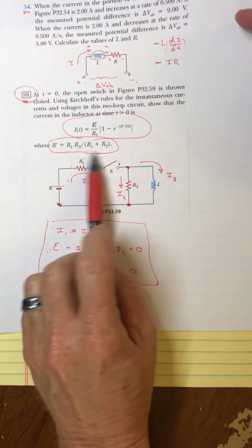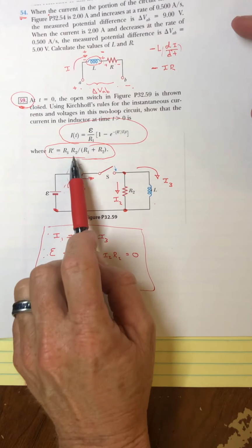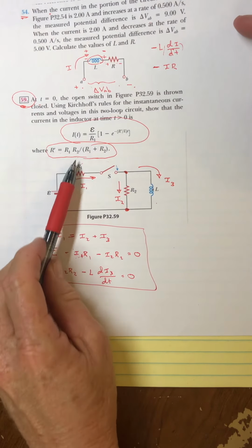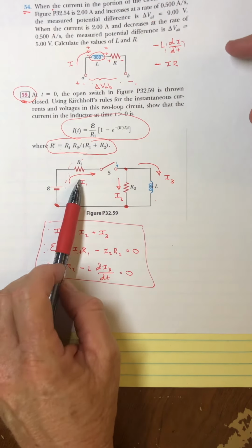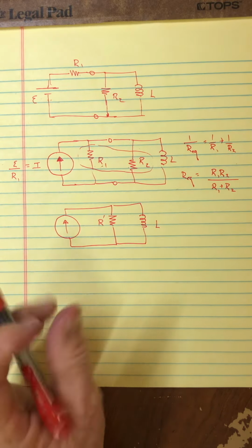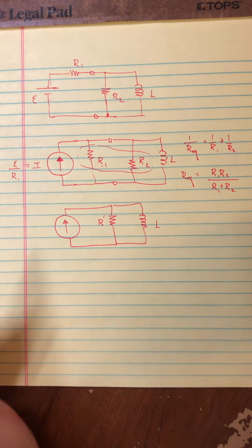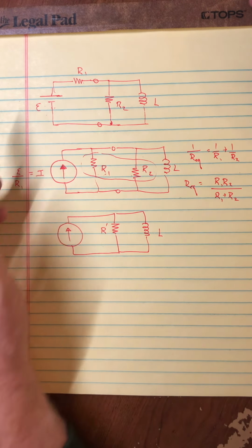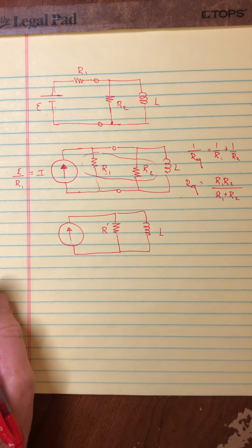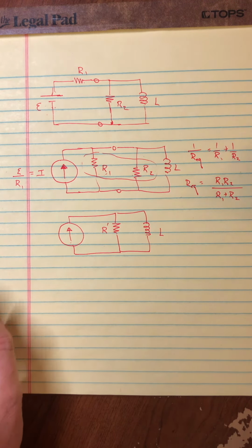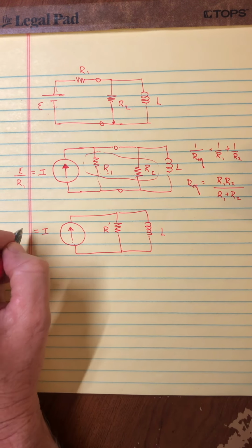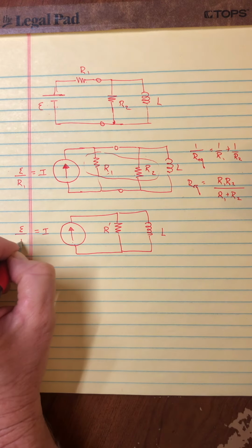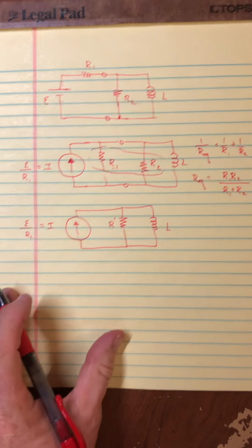And so now you begin to see where that comes from: you're really taking these two resistors and treating them in parallel. But how do you justify that? Well, you justify that by re-looking at the problem not as a constant voltage source, but as a constant current source. Now, I would take one more step here, and keep in mind that the constant current is E over R1.